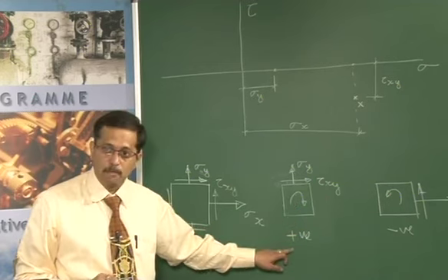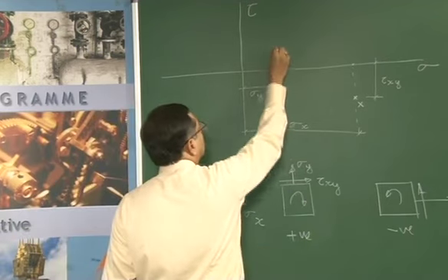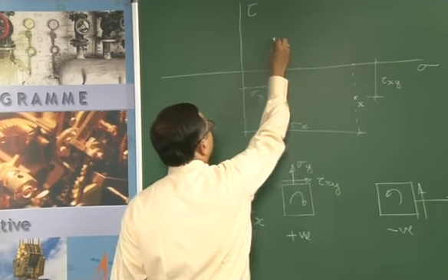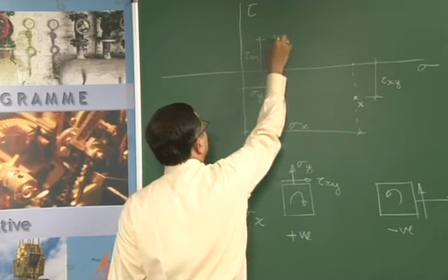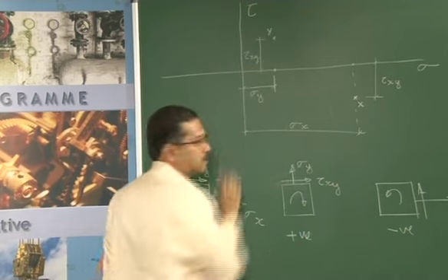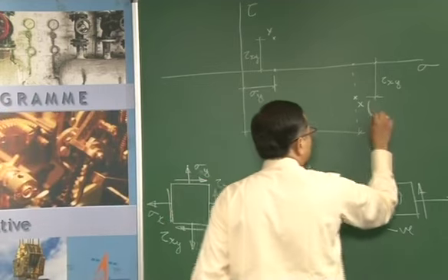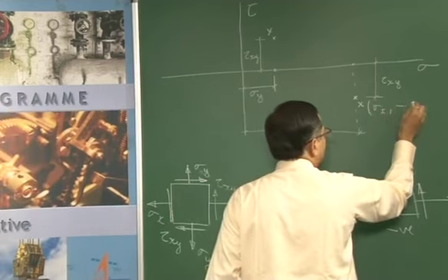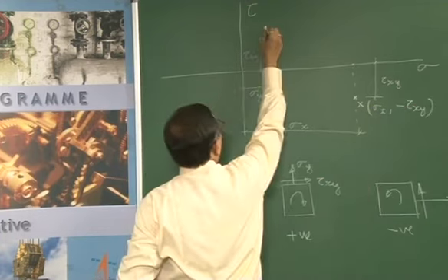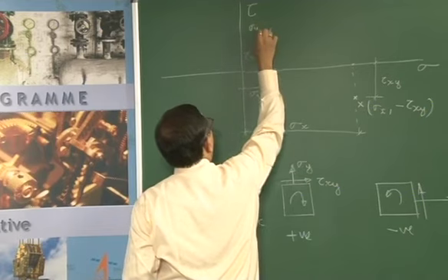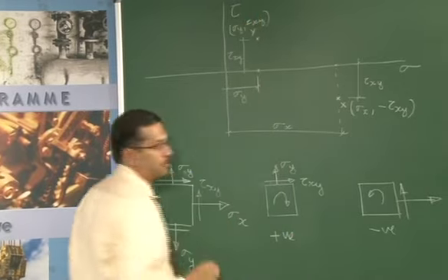So clockwise rotation, because the shearing stress is taken as positive, I have to plot this above, which would be the same value, tau xy. This corresponds to the y axis. Now, what are the ordinates of x? The x ordinate is sigma x comma minus tau xy, whereas the y ordinate is sigma y comma plus tau xy. These are the ordinates that we have.